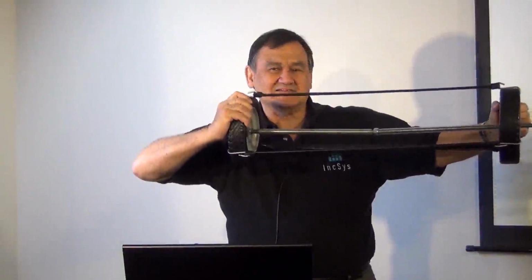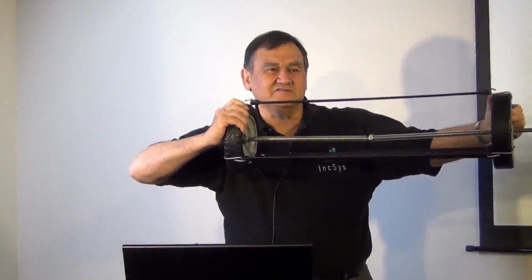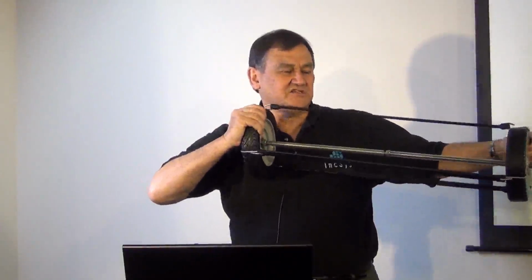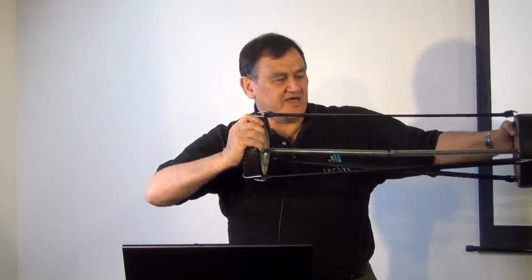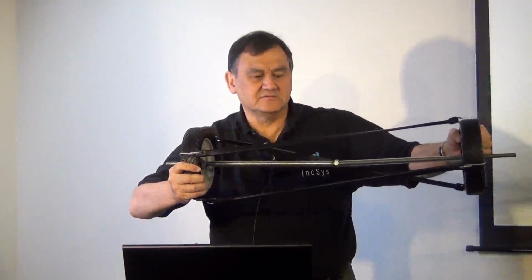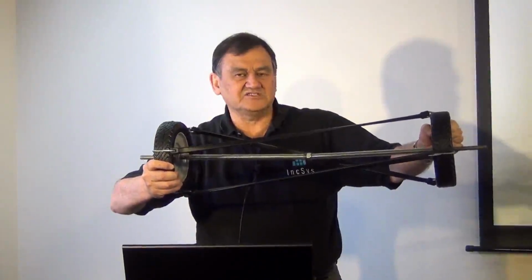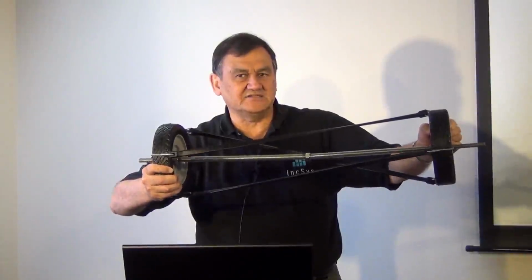This is the angle at the sending end. This is the angle at the receiving end. This distance in the middle is the voltage magnitude across the line. And notice, as I advance my angle, the voltage at the middle of the line is dropping. I get to 90 degrees, and my voltage, I could actually work it out, is 0.707, 1 over root 2 at 90 degrees. But then look what happens when I go to 180 degrees. My voltage at the middle of the line has gone to 0.